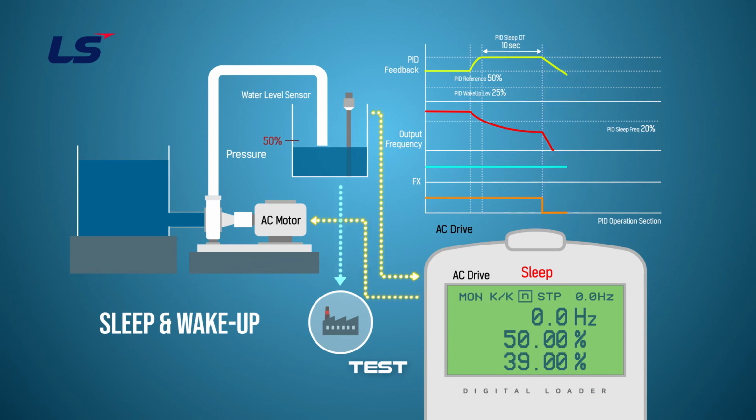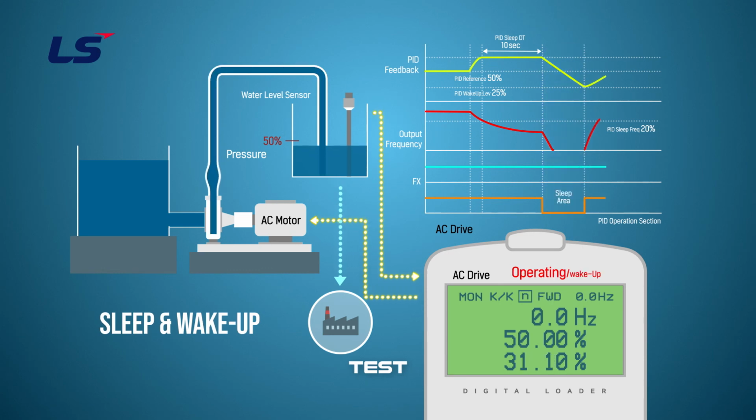In the sleep state, if the water level in the right water tank decreases due to some reason, and the PID feedback value is less than 25%, the inverter restarts.